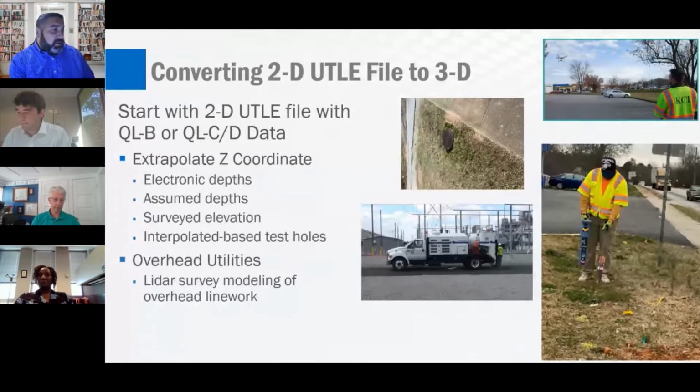In addition to these two methods, we can physically search the project site for utility structures such as vaults, manholes, things of that nature that we can then open in order to collect utility depth data. Performing test holes is typically done when we need to basically true up, so to speak, the depth at which we have the utility depicted, or if we find later in the project cycle that there's a conflict between a design feature and an existing utility, and we'll talk a little bit more about that here.